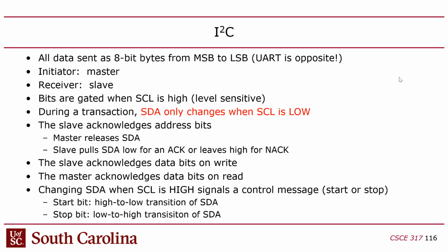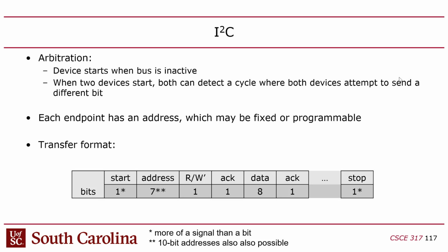So let's see, I already covered that. I2C is serial, 1 bit at a time. It is synchronous, which means there's a clock. And it is multi-master, which means you can have multiple devices on the channel, and you can have any device be a master. With I2C, all the communication is in transactions. So there's no notion of an exchange and a transaction as there is with SPI.